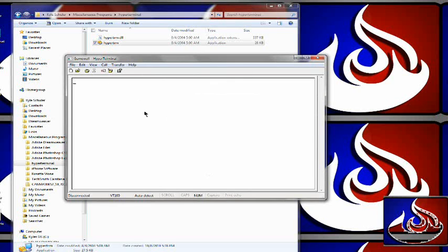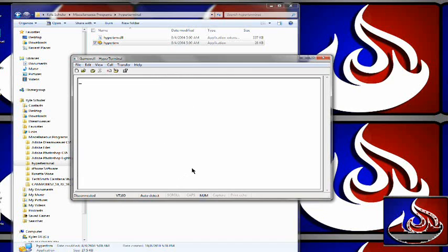Now if you are successfully connected with a programming cable to the Gamewell 600 series control panel, which I'm not, at this point you would just hit the Enter button on your keyboard, and that will bring up the programming screen off of the 600 display. You can enter the password and go through all the programming options and screens in the 600 series program on your computer.